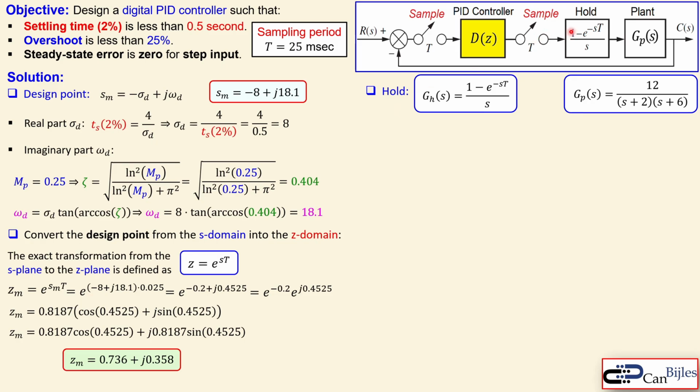The holding operation, let's continue with that one, is given already in the block diagram here, which is the transfer function here. So GH is the transfer function for the hold, and that's required in order to hold that sample. This hold is a zero order hold, which samples a specific value and holds it as a horizontal line. That is the most simple way of holding a specific sample. So the sample and the hold and the plant transfer function together will make the z transform of our plant.